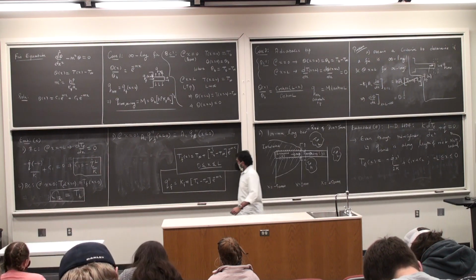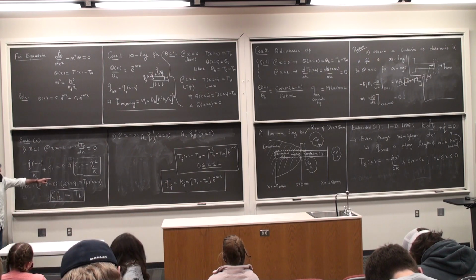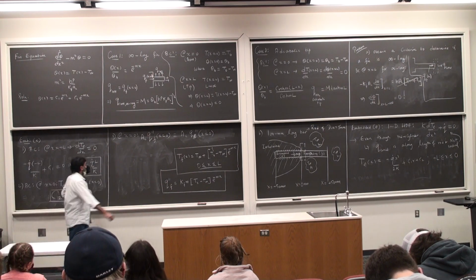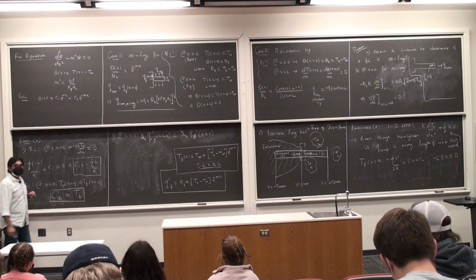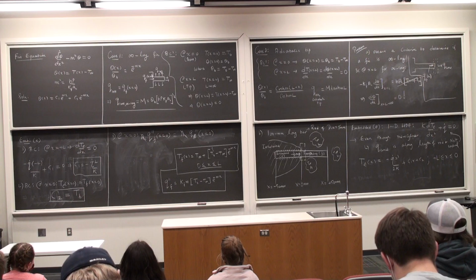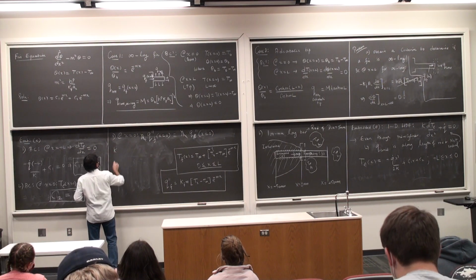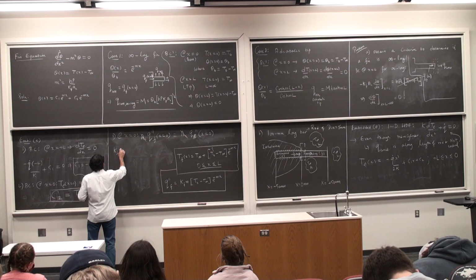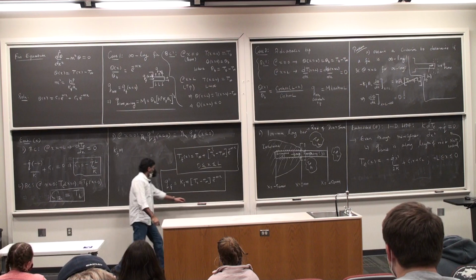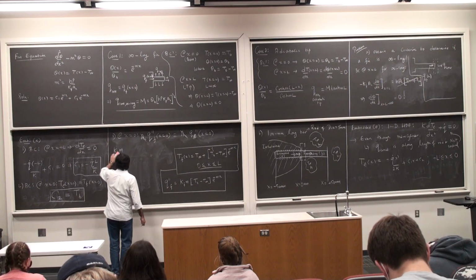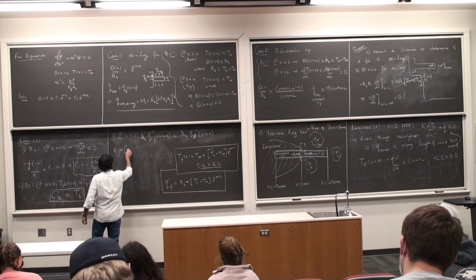Alright. So let's do this very quickly. I already have an expression for Q double prime fin. Cross sectional area is the same on both sides, so I cancel it off. This is the energy balance, the surface energy balance. Substitute for x is equal to 0, so this is Kf times m. Kf is the same as K, so I can just write it as K times m times Tb minus T infinity.